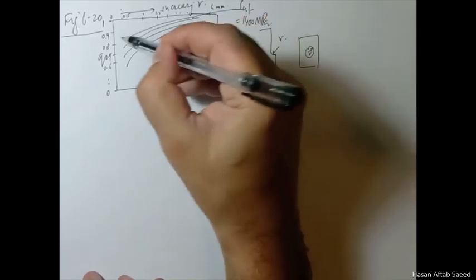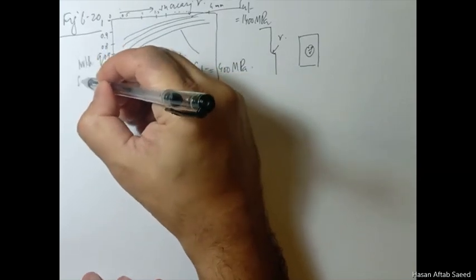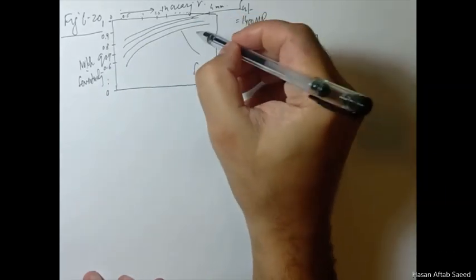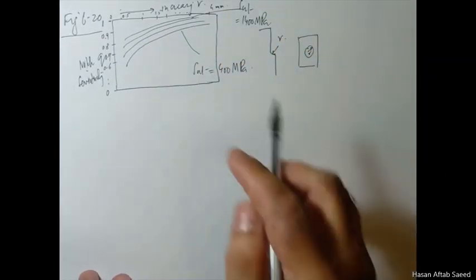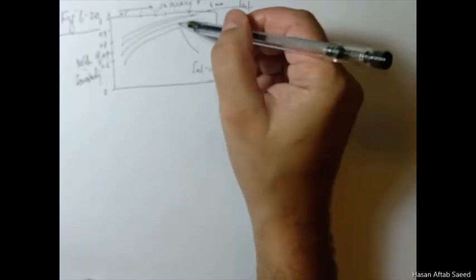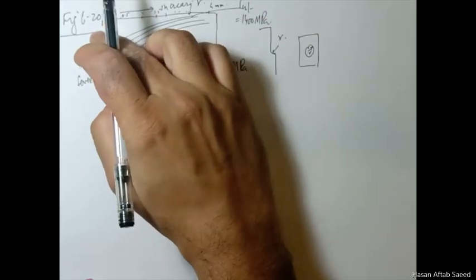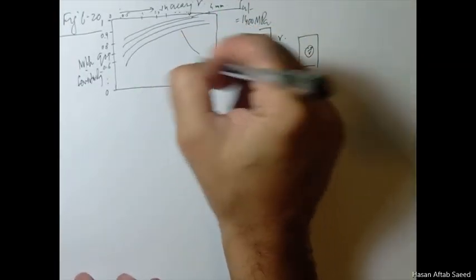So you have less notch sensitivity, as should be the case. And the so-called harder materials, and I don't use the word hard in the technical sense, the materials with higher tensile strengths, are generally less tough as compared to these ones.